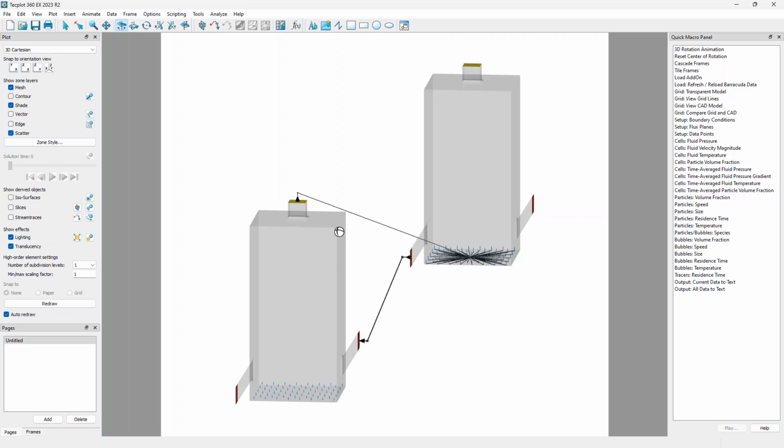And then the other BC connector is intended to take the fluidizing gas that's being injected at the bottom of Reactor 2. It will take that gas and use it as the fluidizing gas of Reactor 1, and it will also communicate any pressure changes from Reactor 1 back to Reactor 2 with a pressure drop. So just keep that in mind. That's what we're trying to do with this particular setup.